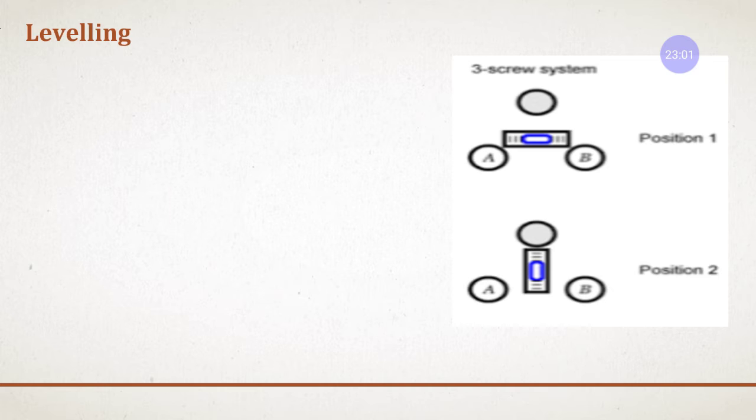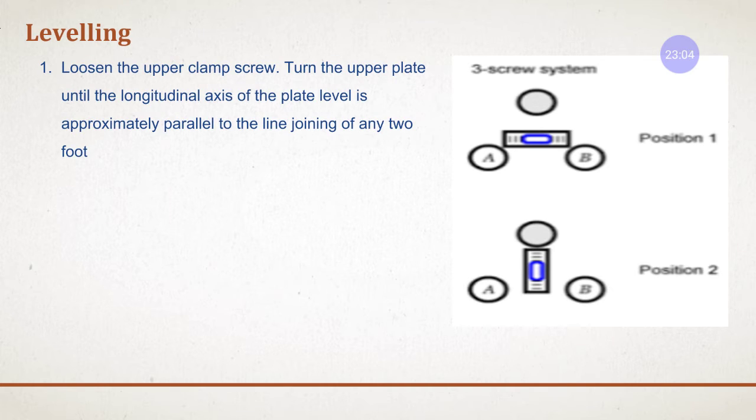Next is the leveling, right? Loosening the upper clamp screws, and turn the upper plate. Okay, turn the upper plate of the plate level, right?